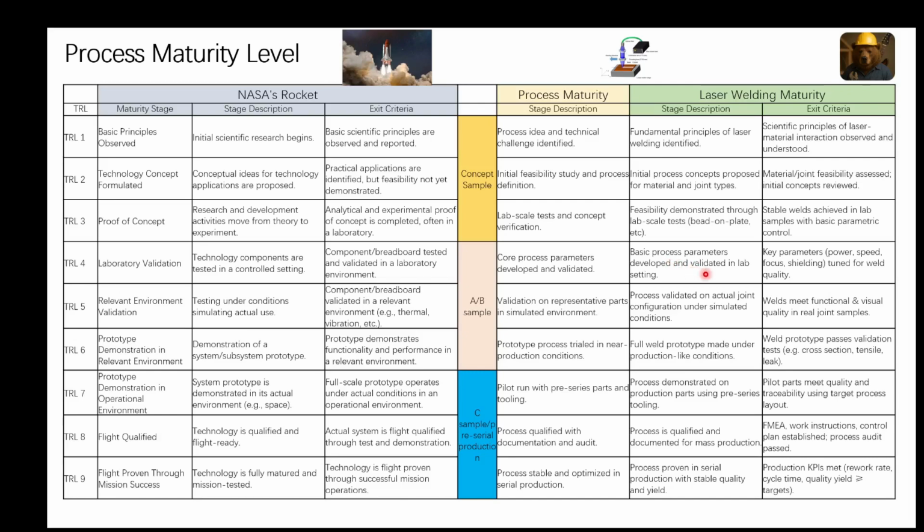You need to try it on an actual machine that is already on the market. So you try your product on an existing welding machine, and you get the process parameters. If no such machine exists, you can ask the supplier to develop one for you.